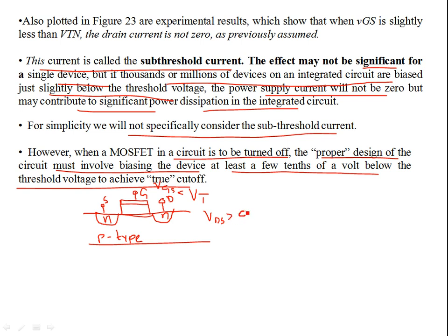So what happens is that this PN junction creates a diode barrier, which is reverse biased by the substrate. But as you go on increasing VDS, for a very small channel length L, this depletion region increases. So it goes like this, then it goes like this. VGS is still less than VT. We don't have an inversion layer due to the field effect at the gate. But if it is increasing like this,